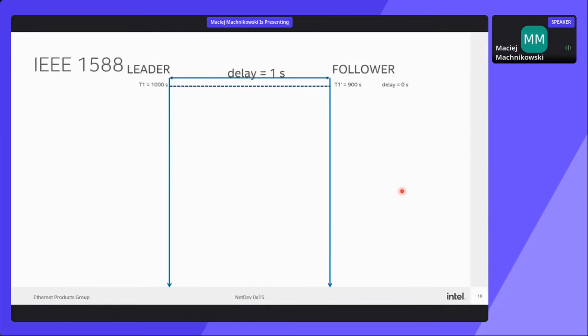And I will go very briefly through those slides that actually talk about how the 1588 works. So let's assume we have our leader side and our follower side, and they are out of sync. And let's assume that path delay is 1 second for easier math. So the first thing where the 1588 starts is that we will receive the sync packet from the leader, and